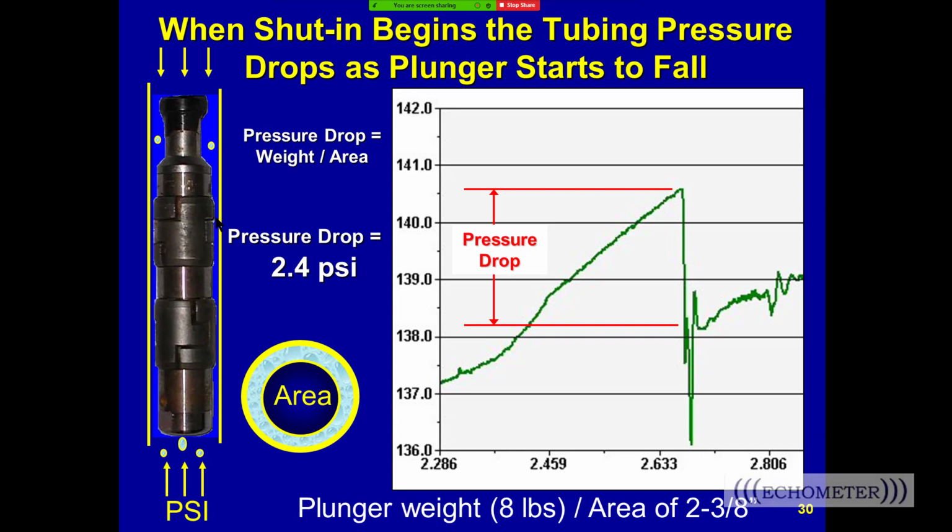That's very efficient. Okay. And another question is, the wells that come up dry, is it better to add downtime and increase afterflow? And this is specifically for a well with 2 3/8 single pad. Well, sometimes when the plunger comes up dry, it's not because there's too much energy.